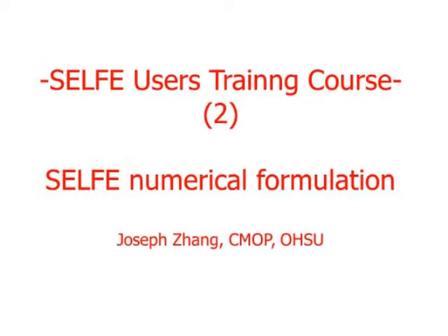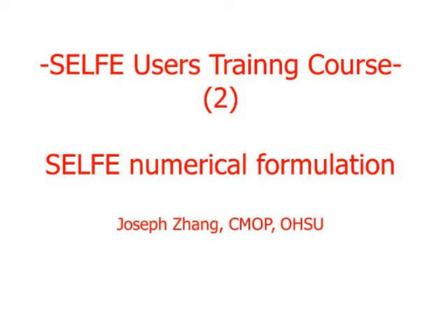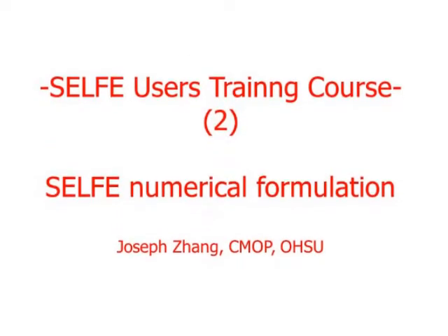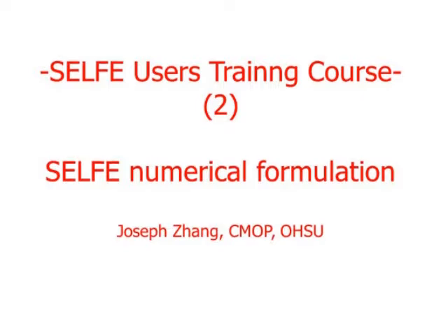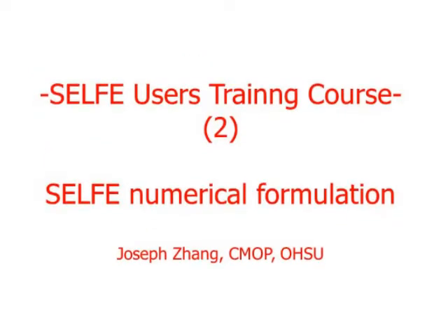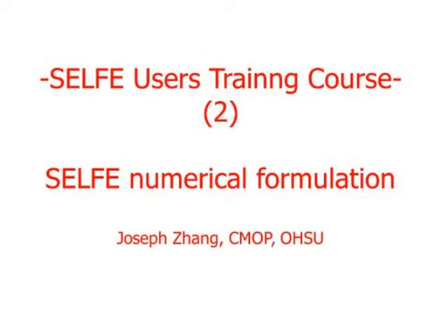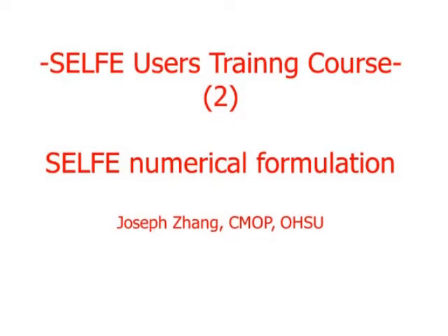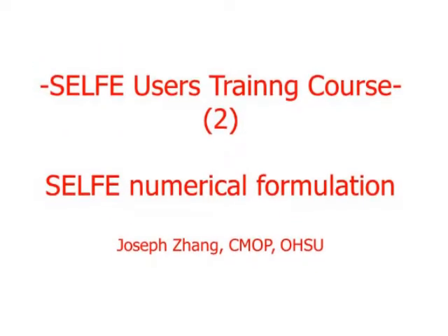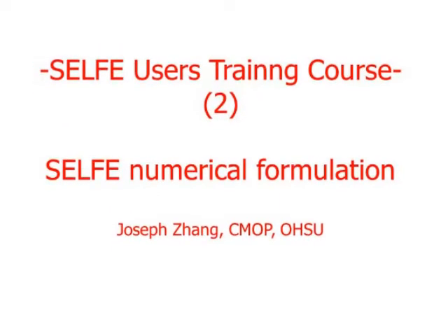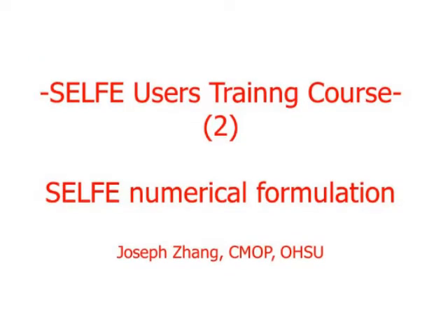That's for the momentum equation. You need to solve momentum equations later. So for that, you need to do another set of averaging. Pick a side center and then average around its two adjacent elements, and of course you need to do proper vertical interpolations.